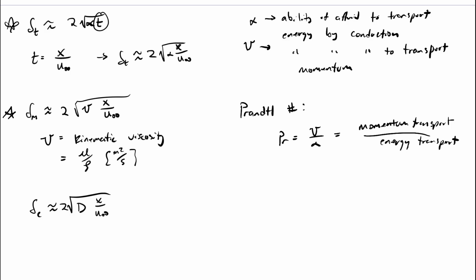One example that I think is important is, let's talk about air for a second. Air or any other gas is basically an ideal gas. What are the mechanisms for transporting momentum? Physically, what's happening? The molecules have to bump together. They're relatively sparse. They have to physically come together. What are the mechanisms for transporting heat? It's about the same thing, right? They physically have to come together. So the mechanisms in an ideal gas situation are basically the same mechanisms. So anytime you're transferring momentum, you're transferring heat.